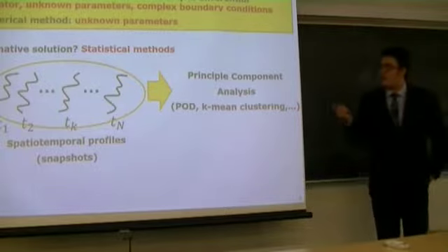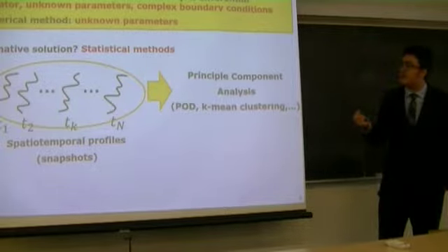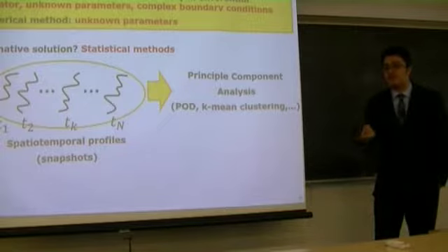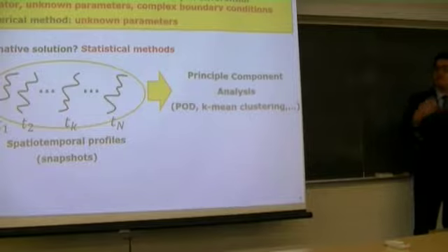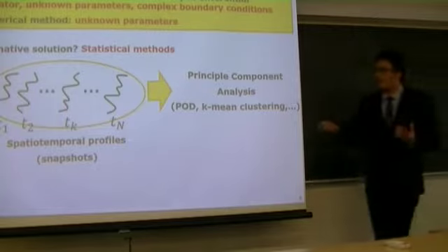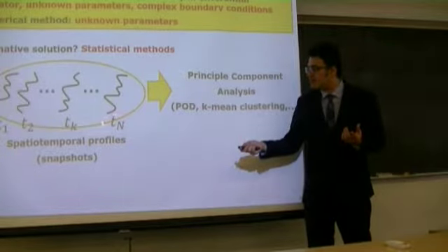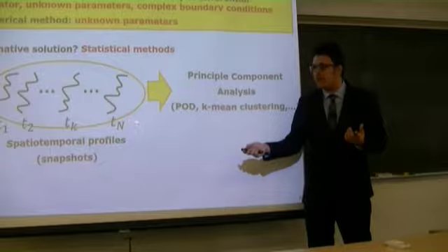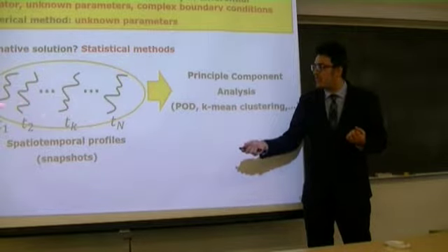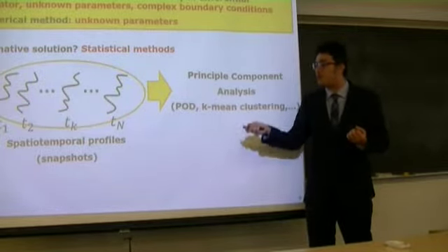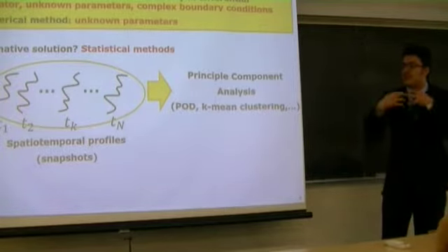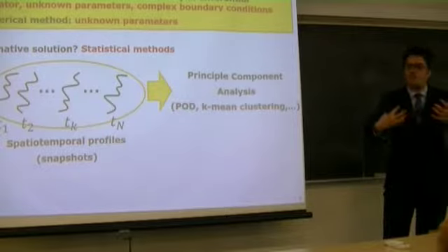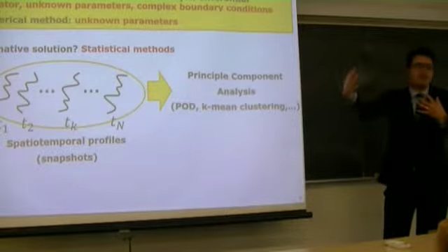But the important problem here is that if you want to do it offline, there are some situations regarding the dynamic behavior of the system that may not be captured in offline calculation. For example, you could not find a sufficiently small number n for the number of spatiotemporal profiles needed to get more accurate basis functions. So there is a need to revise those basis functions during the process evolution based on the data from the system.